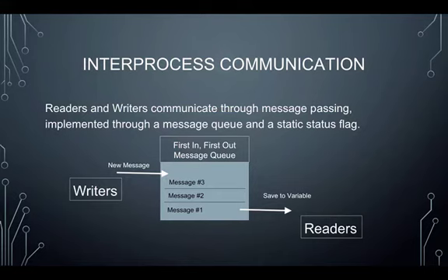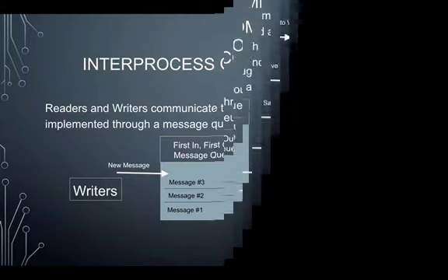Another thing that we have implemented is the status flag. This allows each task to report its status to the global system without interfering with the interaction of another task. This is implemented through a status flag variable in a function that all tasks can call. Each task interacts with this status flag in strict accordance to the reader-writer schema. While every task can read the status flag and see what that is, only the task associated with that motion can set or clear its specific flag variable.